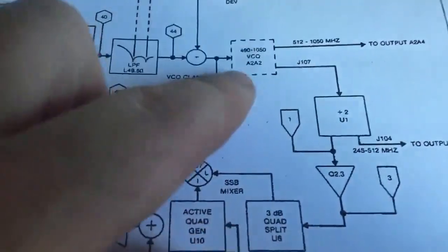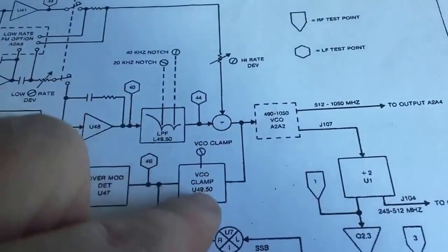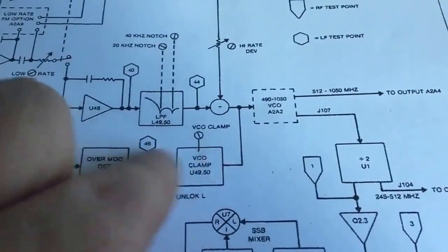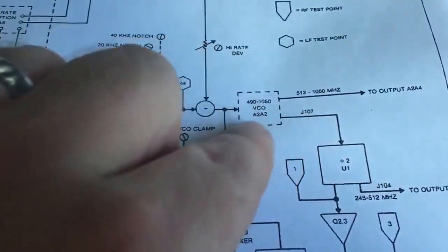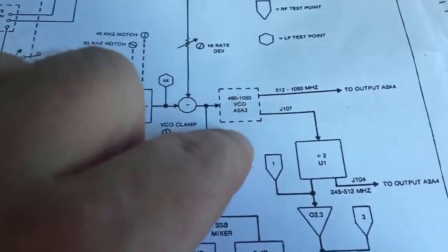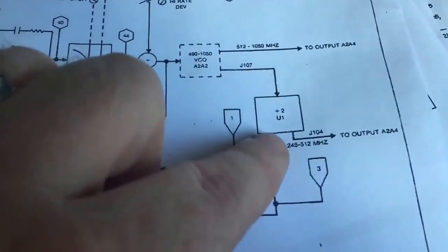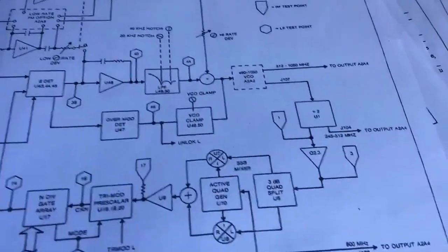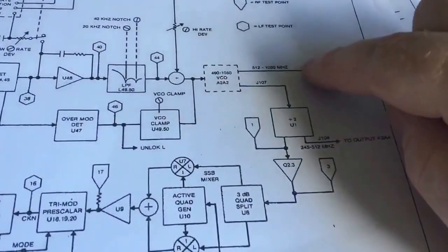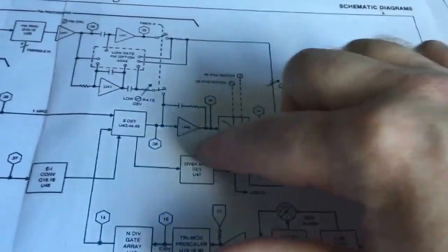that's the main VCO, which I know is wrong. Let's sort out the circuit I was probing before here. There's a VCO clamp and stuff like that. So that's where the VCO output is in error. I know that every VCO is wrong. So here we go, divide by 2 right there. Okay, so that means the fault has to be before that VCO, as I'm suspecting anyway. So that just confirms what I've been suspecting. So I know that after this point it's fine, after that point it's fine, because the only common thing is from that VCO and all this leading circuitry.